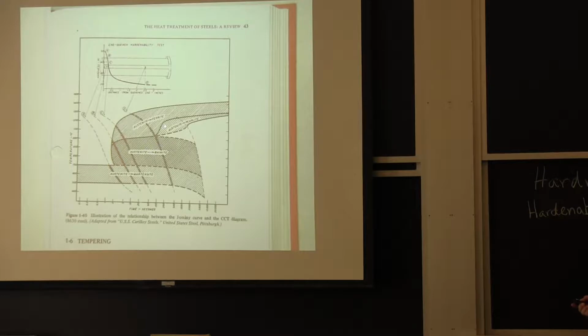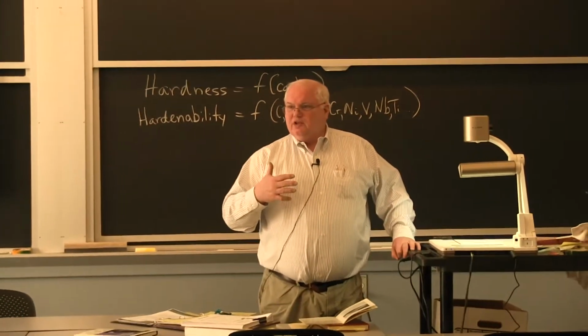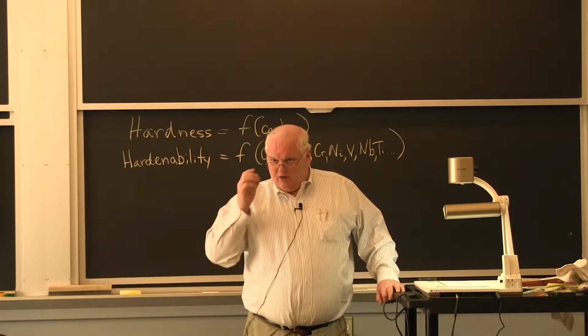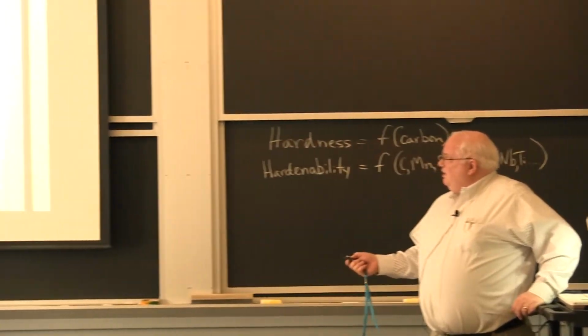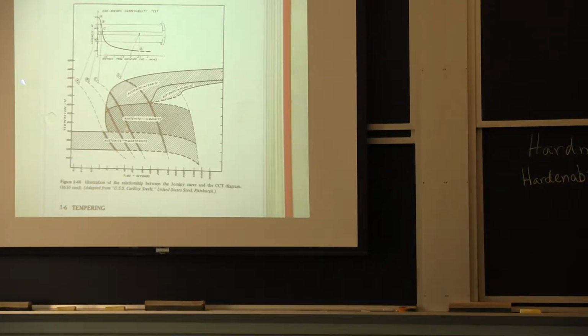You sometimes like to get bainite, but you're going to get a transformation when you weld, okay, in the steel, and that transformation can lead to excellent weld matching, so you can get same strength as the base material. You can't always get that in, say, some of the aluminum alloys, but systems that have a change in crystal structure from one crystal structure to another, such as the iron-based systems or the titanium-based systems, you can usually get matching strength between the weld metal and the base material. And so that's one of the advantages, an advantage that the iron-based system has.